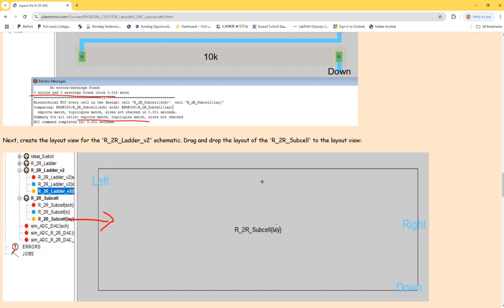It doesn't show the details, and there's a way to show the details. You select it and there's a button on the top. You can click and it's going to show the details of the layout. The thing is, on the upper level, whenever you reuse the layout icon, even though you can click a button to show the details of the layout, it's not editable. You cannot edit. If you want to edit anything of the layout, you have to go back to the subcell's layout to edit all the details. Which makes sense. You don't want to add anything on the top. That's the goal, right? Whenever you see issues, you always want to go back to the subcells to change all the details or errors. So these are just higher level icons of the layouts.